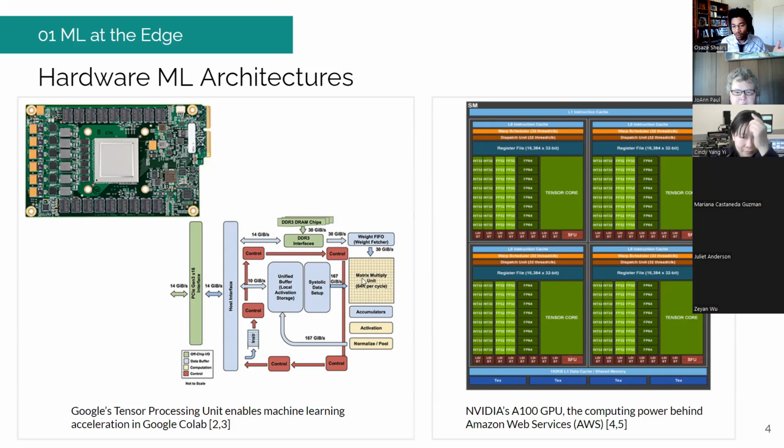So they have batch matrix multipliers, an array of these matrix multipliers, since that's a pretty frequent operation that's done for a machine learning task. In addition to a lot of different control logic and memory management logic that allows you to access the different weight values and the different outputs of various machine learning layers and neurons. So this is a pretty typical architecture, and a lot of research papers have gone on to explore variations of this architecture.